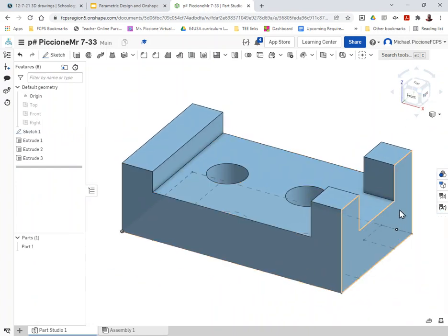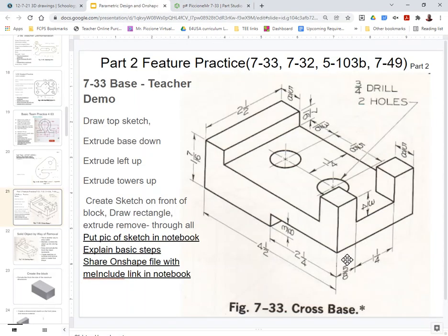So that's most of our shape. We've got the shelf on the left side and the 2 towers on the right with the circles in the middle. The only part we're missing is this little cutout underneath the bottom side. There's multiple ways to draw this cutout, but I'm choosing to draw it this way so that you get used to using this extrude cut method that we may see later. And I see that the cutout is 3/8 from the bottom edge and 2 1/4 from the right side.